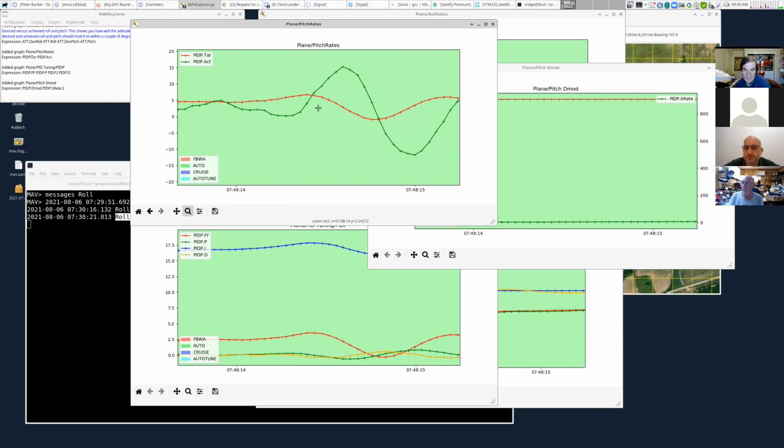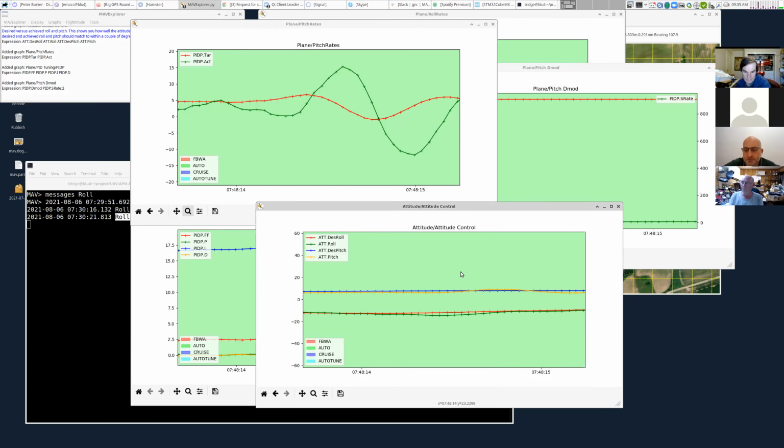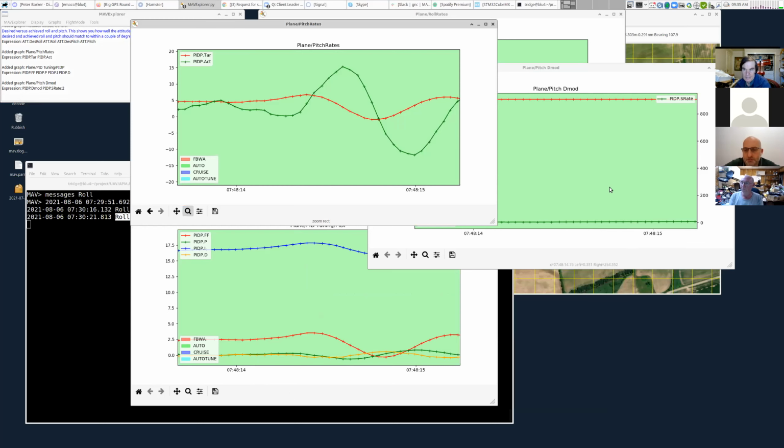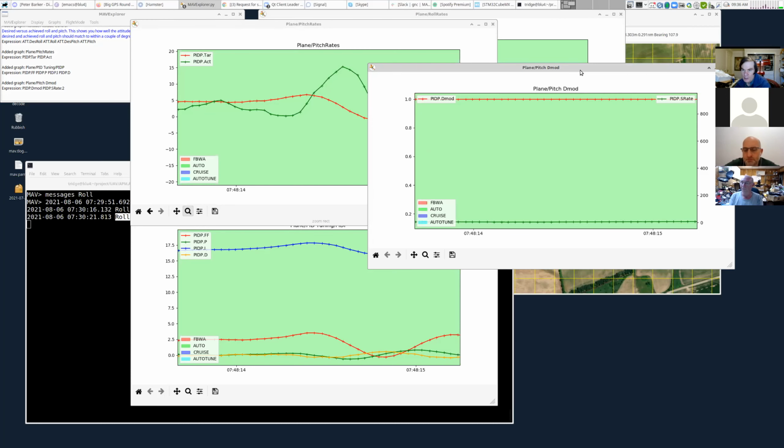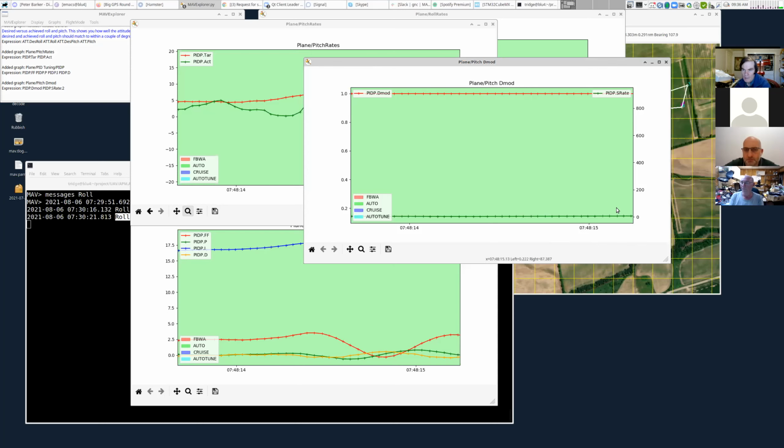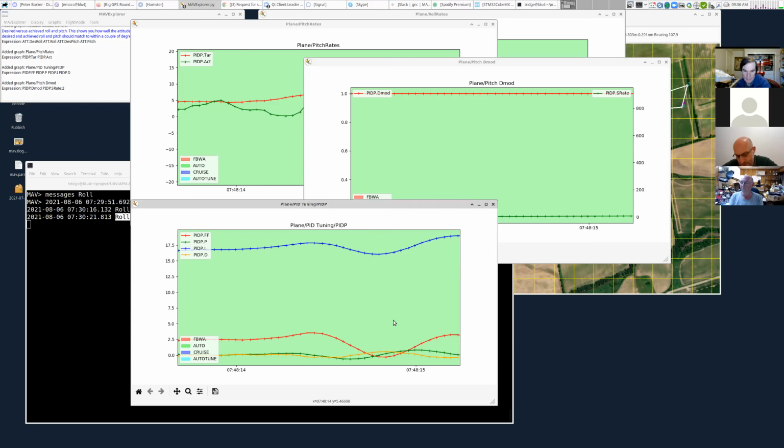And when I see that type of response, that usually says to me that feed forward is not going to help it very much, because most of it's just the response of the airframe. Feed forward doesn't help you if it's just the airframe responding to a gust, but what helps you there is gyro feedback or damping, which is essentially the P term. Right. So we can see here that if we look at the slew rates we've got on the servo, it is very, very low. We could almost certainly raise the P and D somewhat higher than what the auto tune gave.